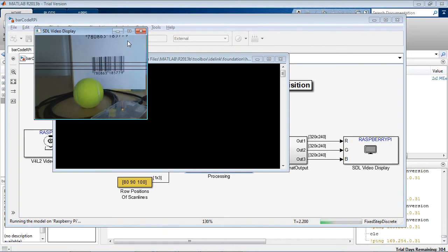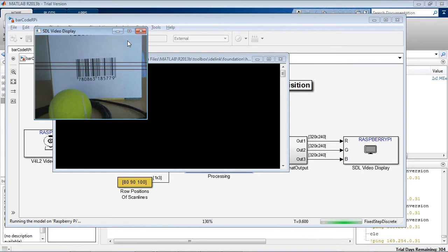Let's see if I can get this zoomed in and reading. Okay, I've kind of adjusted it so it reads correctly. You can see that prefix is a 9. And it's basically scanning that barcode, translating the bar graph, and outputting in numeric digits. So that's pretty clever. The reason you have to move around the webcam or enlarge the barcode is because webcams that you typically buy online have a fixed focal length or do not autofocus. Their typical focal length is around 40 centimeters. So you need to get it set up correctly so it can read the code.